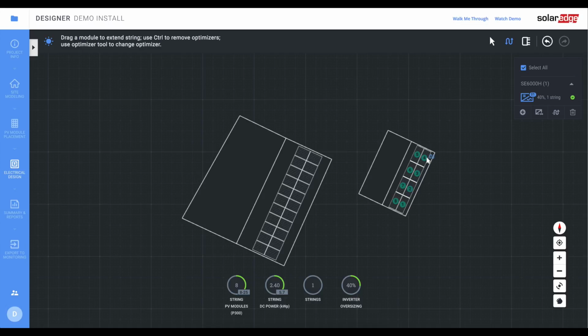So as I said earlier in the video, ideally I would increase this string a little bit to incorporate a couple of these panels in that string. Now the reason for this is in the connection to the inverter, I believe that by default there is only 2 connection points for 2 strings.